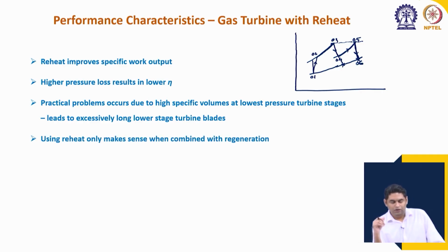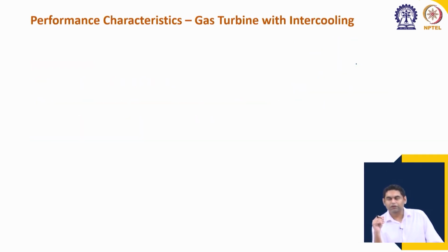And as I was saying, using reheat only makes sense when combined with regeneration. Now, for intercooling, the behavior is similar to reheat. So, we are not going to repeat that part. The behavior is less excessive, meaning the loss in efficiency is lesser, but the gain in the work output is also less, and intercooling makes a lot of sense when combined with regeneration.